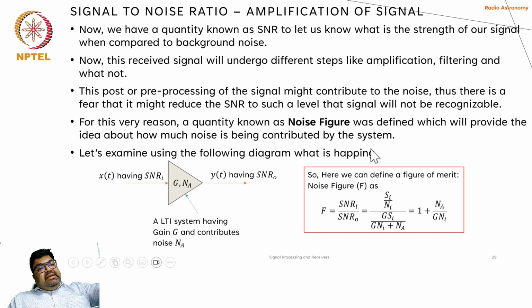So the signal is coming from the sky. It gets detected by the antenna and then pushed through the front end and back end electronics, which amplify, filter, mix the signal, with a square law detector, etc. There is a lot of other electronics. While passing through these different stages, the signal also suffers attenuation, and the contribution of noise in the signal increases because of the system itself.